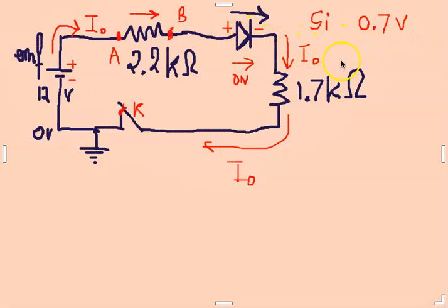Now, in some cases, we can also have a germanium diode. If you have a germanium, the drop is just 0.3 volts. So what does it mean? Let's specify, for example, that in our case we have a silicon diode. So we are expecting a drop of 0.7 volts.